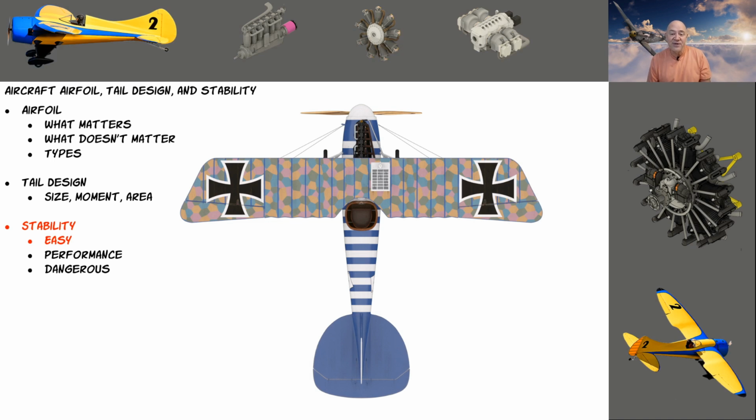Okay, so I've always considered any biplane, as long as I got to be careful, I open up this can of worms. A lot of biplanes, depending on where the top wing is, will either have positive top wing incidence or a little bit of negative. But it has a lot to do with where the wing is in relationship to the other wing. Some biplanes that have ailerons on the bottom wing want the top wing to stall first. That way you don't ever lose aileron authority. So the top wing is actually 1 degree higher than the bottom wing. But I'm not going to go into all that right now.